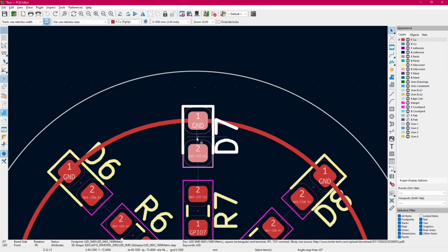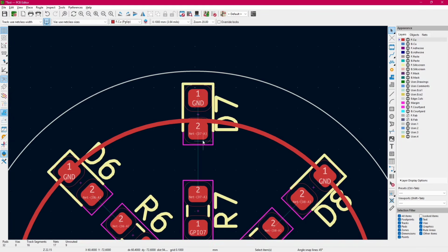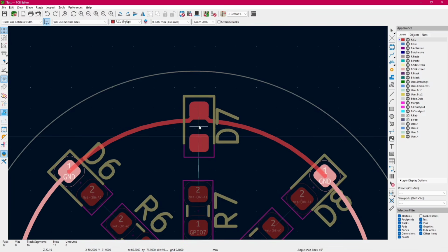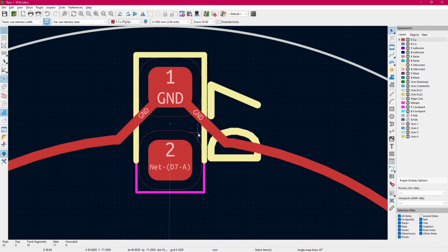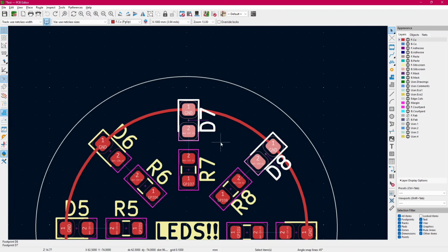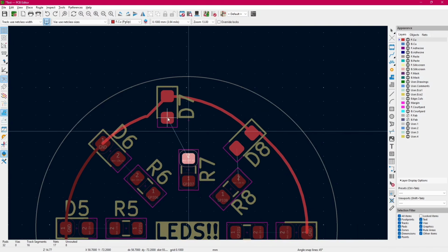If you try to move a component, for example up there, you can see that the trace didn't move with the component. So how can we move both of them? Well, it's easy. Just press the D key and you can see now we are moving both the trace and the component. This also works with 2 or more components, as you can see here.